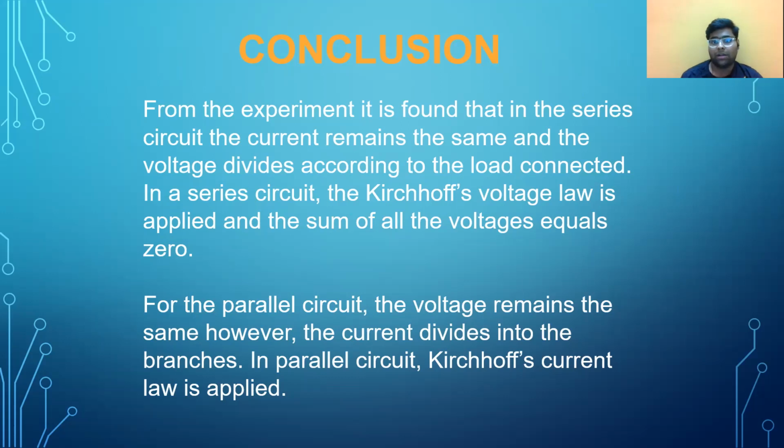It is found that in the series circuit, the current remains the same and the voltage divides according to the load connected. In a series circuit, Kirchhoff's voltage law is applied and the sum of all voltages equals 0. For the parallel circuit, the voltage remains the same, however the current divides into branches. In a parallel circuit, Kirchhoff's current law is applied.